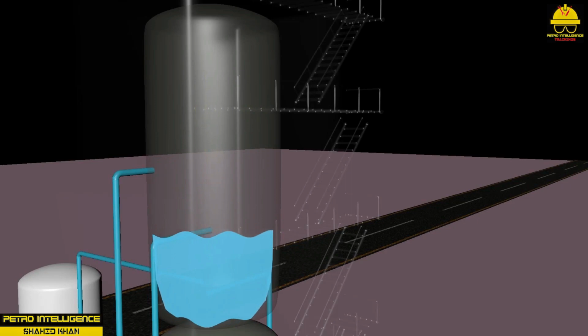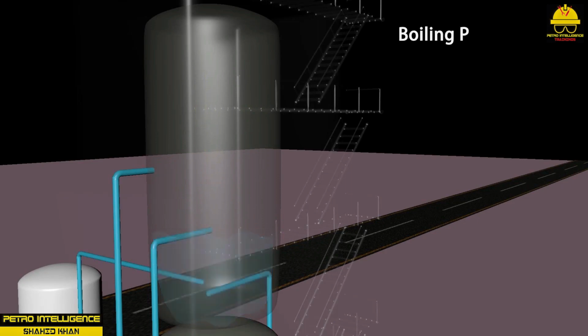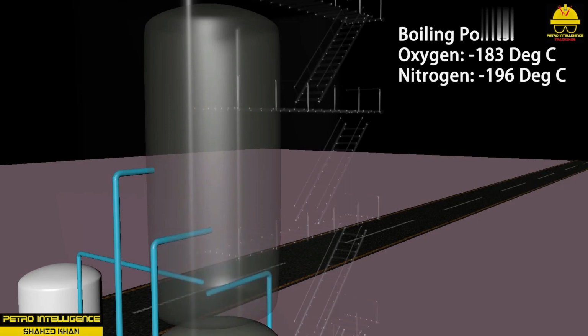In the nitrogen cryogenic process, the warm end process is the same. However, upon entering the cold box, the main heat exchanger rapidly cools the air to -165 degrees Celsius. Nitrogen collects in the top of the column while oxygen pools at the bottom. Liquid nitrogen is sent to and stored in a tank. Refrigeration for the oxygen and nitrogen cryogenic process is provided by an air brake expansion turbine physically located at the base of the cold box. High-pressure gas is expanded to low pressure and cooled in the turbine.